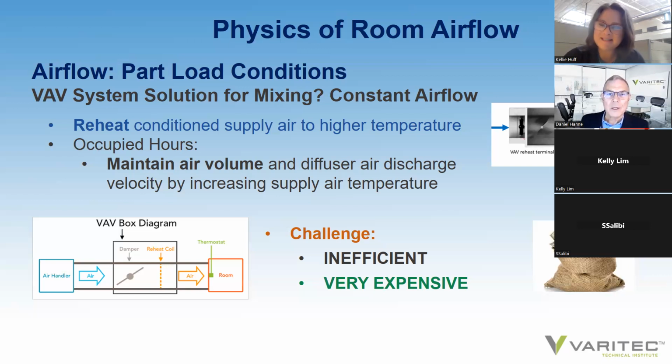Well, that's good to hear, because yes, our manufacturer, Krueger, for displacement diffusers, will actually do throw patterns of air at 40 feet per minute discharge, 20 feet per minute discharge over an architectural space. If we can have CAD drawings of the space, we'll do a throw evaluation through our manufacturer. And for an engineer to look at and to evaluate, it makes all the sense in the world that any representative who is trying to advance displacement ventilation would participate with the engineer in evaluating proper layout.